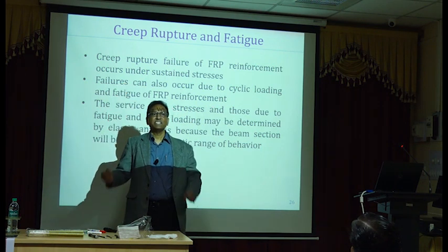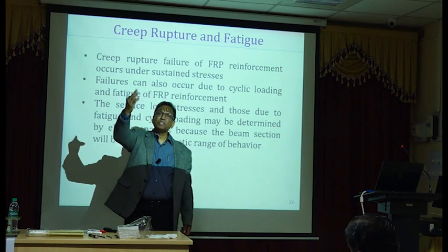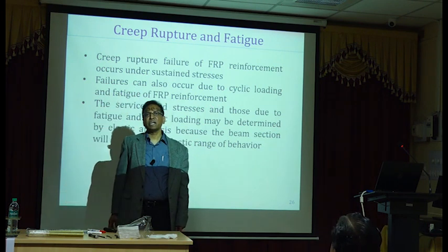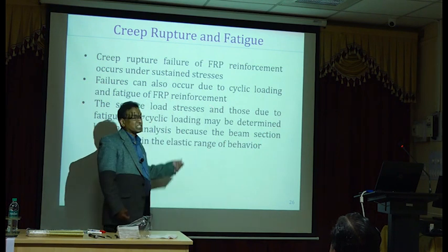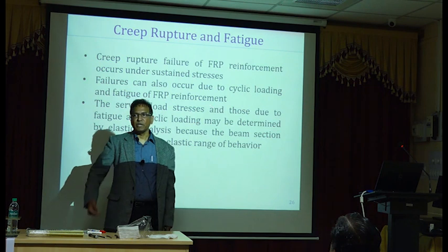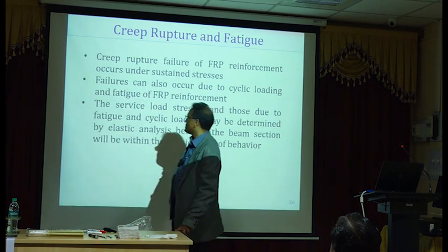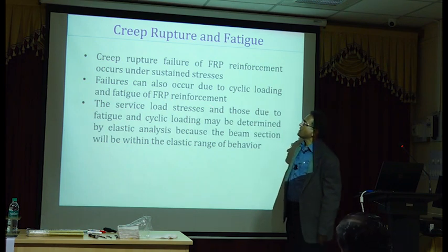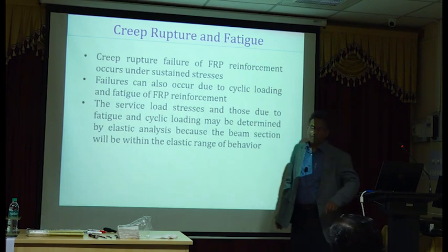Let's say static loading gives you 100 ksi, or 100 units. Under sustained loads, it may fail at 25% of that, which is 25 units. That's a big problem. So in your design, you must consider the creep rupture failure mode of FRP.